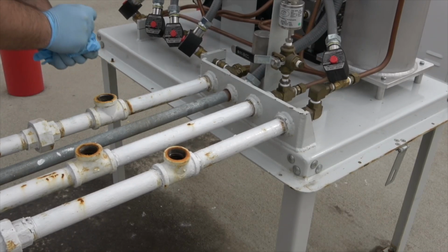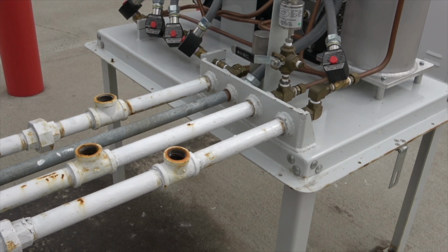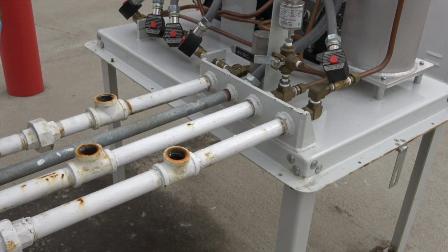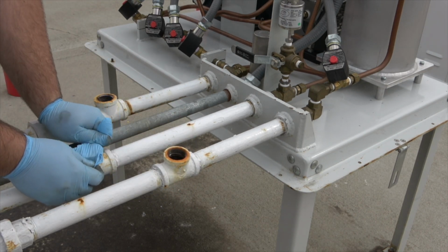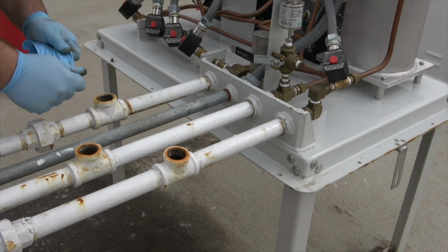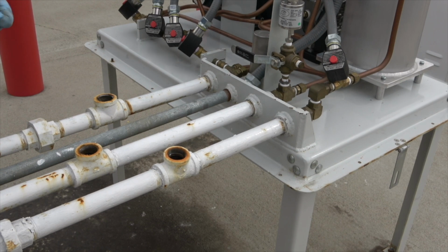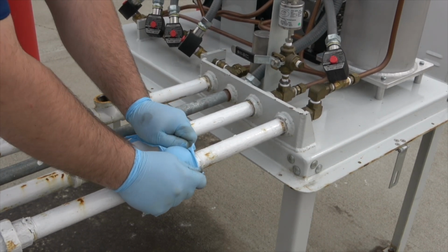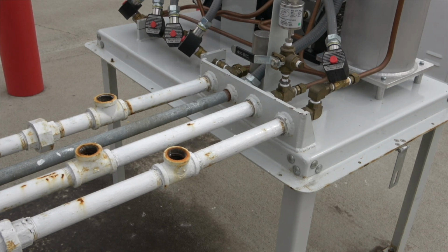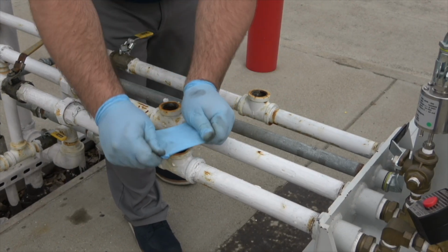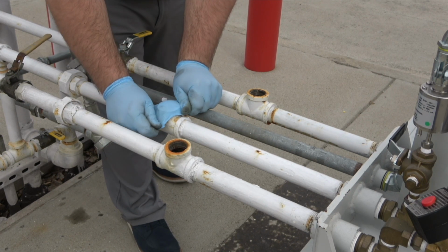During the run mode, place your hand over each open T fitting. You should feel the following: suction at the vapor inlet T, air blowing from the air outlet, and no blowing or suction from the vapor return. If there is suction or air blowing from anywhere unexpected, refer to the troubleshooting section of the Green Machine manual in Chapter 8.